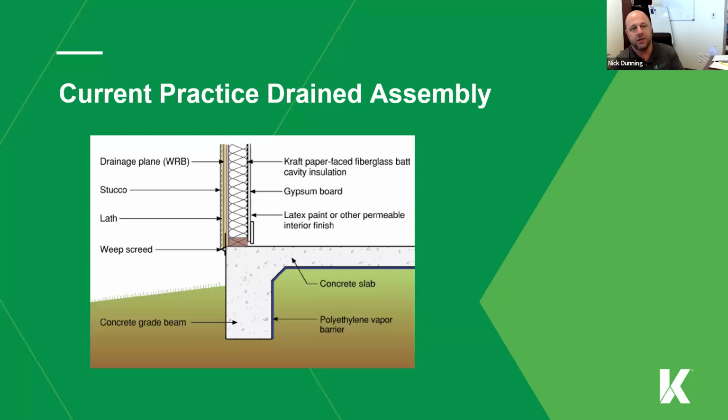So if it has moisture against it for a long period of time, that moisture is going to end up in your unit. So sometimes it's as simple as they built up the grade too much and it's caused all this deterioration. And the flip side of that too is always keep your gutters clean, because that flashing is meant for downhill water. So if you're now clogged and it's going back up, you can get leaks in your walls from a gutter system. So, there are little things like that that will save a lot of money and headache down the road.